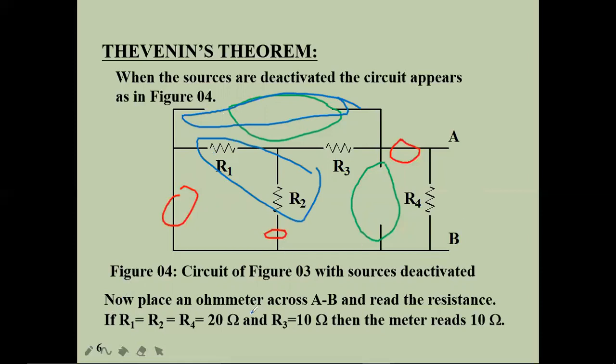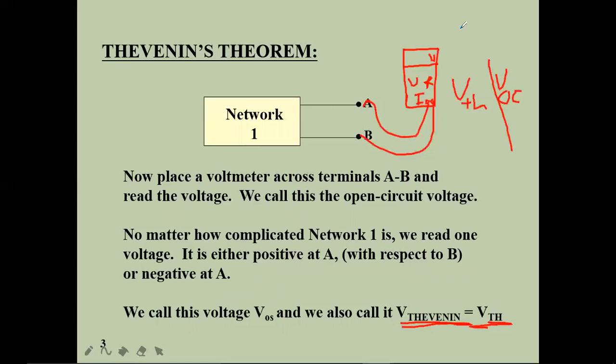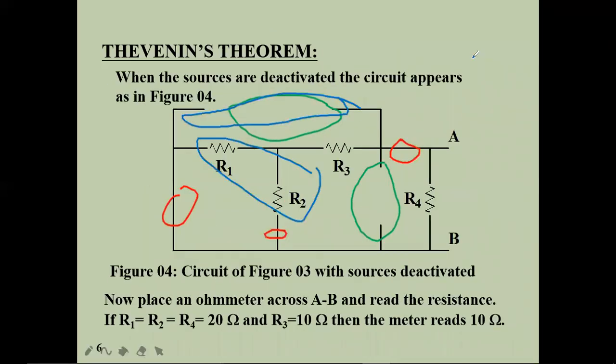Now place an ohm meter over here. You can use a DMM. I already said in the previous session, you can use a DMM. You can use the same DMM by measuring the ohmic value, by using it as an ohm meter, keeping it in resistive mode. Then you can measure the resistance across this directly. That is the practical way of finding the value. But theoretically, there is a procedure, and we are moving to that procedure.